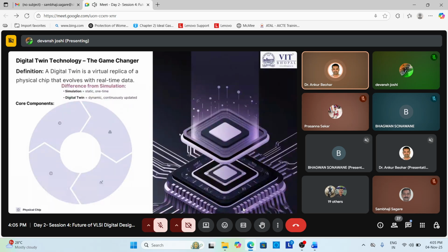describe the testbench simulations, or even formal verifications. Then we go for the tools: ModelSim, Cadence, Synopsys, etc. Where after we successfully complete functional verification, we go for the synthesis of designs.